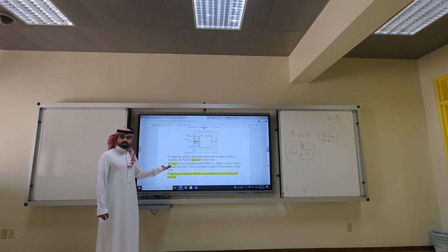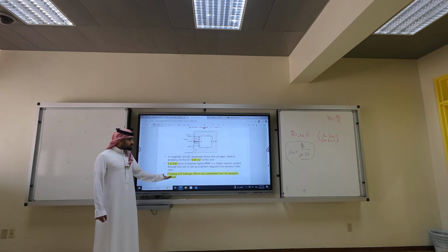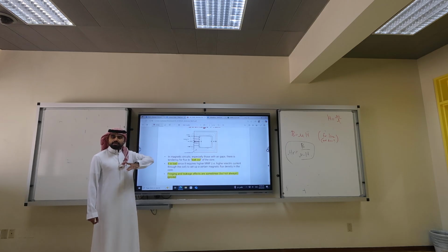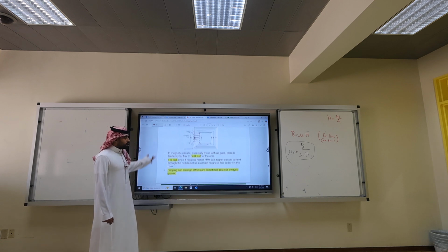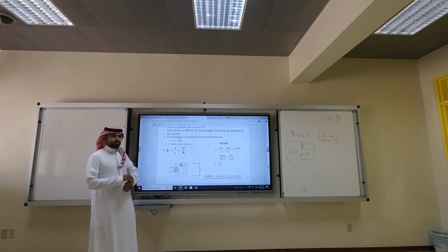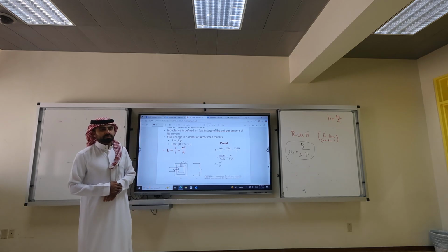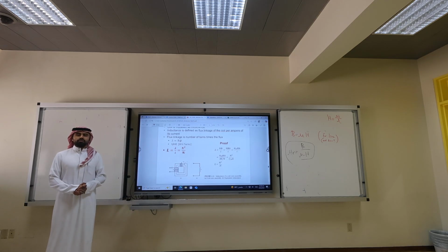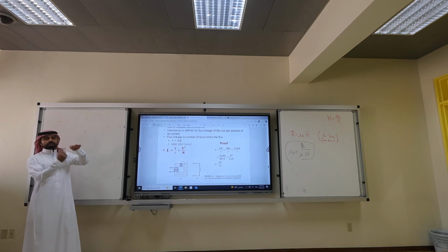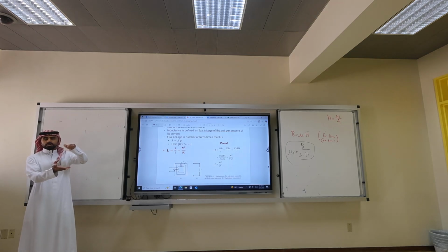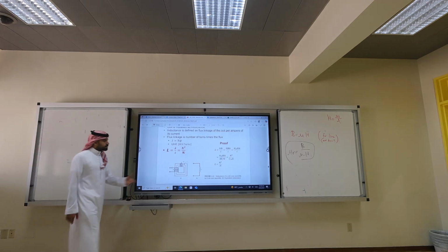They are bad, okay? And sometimes we account for them. Sometimes we ignore them. Get it? Doctor, if I have fringing, is it possible to have more leakage? I don't know, it depends on the problem. But of course, the fringing is big. If you change the turns spacing more, would it change the leakage? Of course. If you put them closer to each other, it will change what we call the flux linkage.